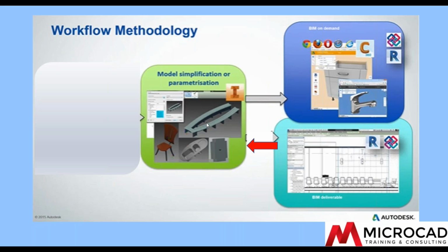The custom products workflow is where the architect designs the product and you just have to figure out how to make it. Using Revit, the architect builds the geometry, perhaps making it a Revit family. The geometry is then linked into the Inventor model and further detailing can be done. As before, if there's a change in the Revit model, it will be changed in the Inventor model also.